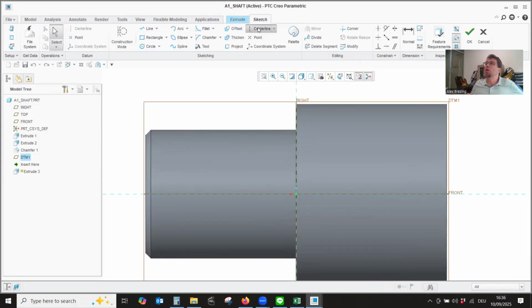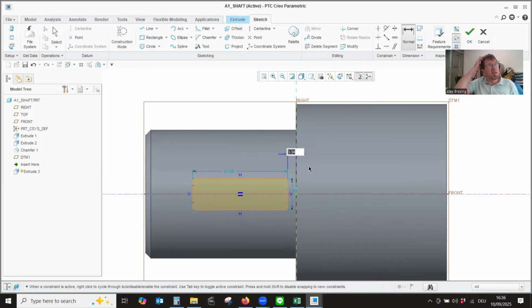And I will use a center line because, of course, this cutout should be symmetrical. And I plan to use the full round command again, so I will not actually sketch the rounds of this groove. The groove needs to have the rounds. In the lecture, we saw the video of how it's created. I think my hub is 45 millimeters long. And what did I just do?